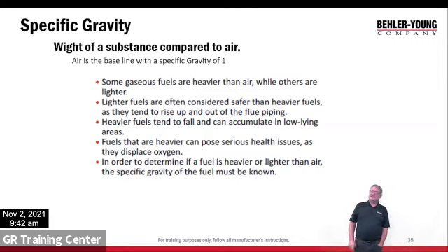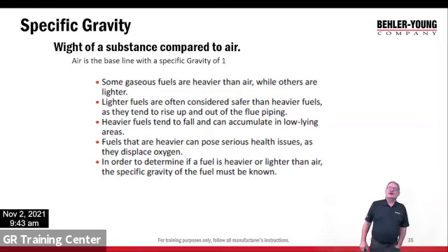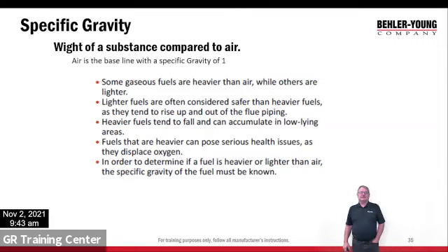Some gaseous fuels are heavier than air, while others are lighter. So you're going to see some are heavier, some are lighter. The lighter ones are a little safer. The heavier ones are a little more dangerous. Okay, so fuels that are heavier can cause serious health issues as they displace oxygen. They do something that is called puddling. And we're going to look at that in a minute too.